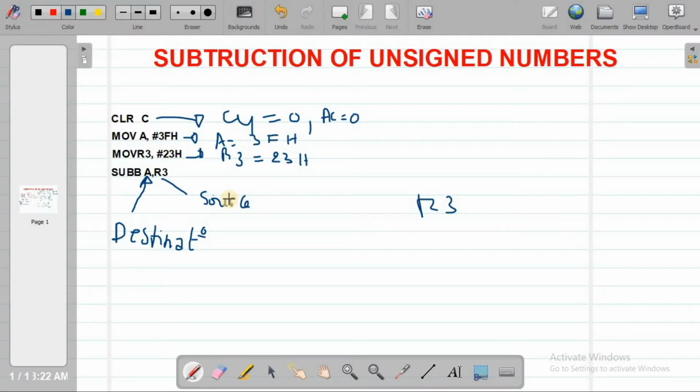So let's go back now here. Let's calculate. In this line, the accumulator is equal to 3F, which is inside the accumulator, and then they subtract 23 from that 3F. Obviously, if you use your calculator, the result will be 1C. When you're using your calculator and they ask you what's the final result, you say it's 1C. But the question may be difficult for you if they ask what's the value of the carry, or show us the calculation.